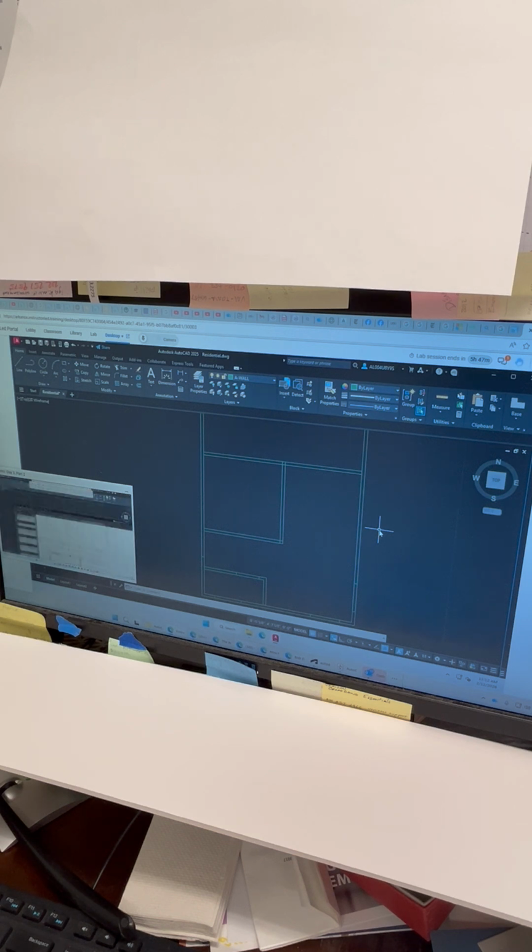So taking a look now, I was able to put in this dimension here and the 3.5 inches. We used the 15'6" dimension to locate the center wall that goes right through the middle of our bedroom plan. We used the 7'9.5" to get the other wall of the closet. And by default, we have defined this 4-foot dimension that goes from the water closet to the walk-in closet.